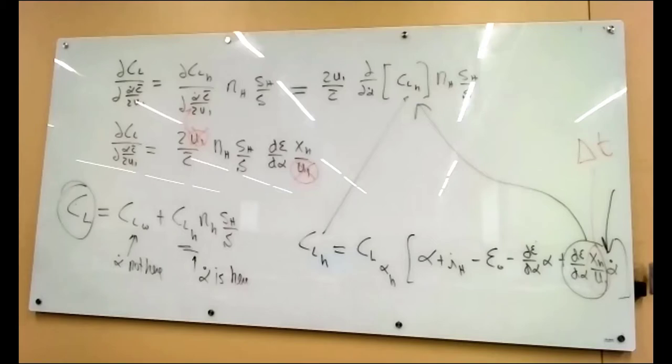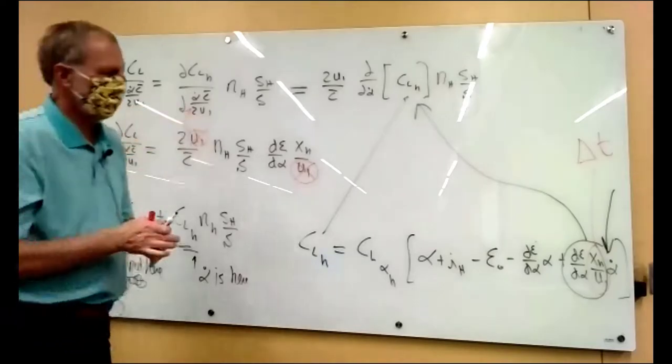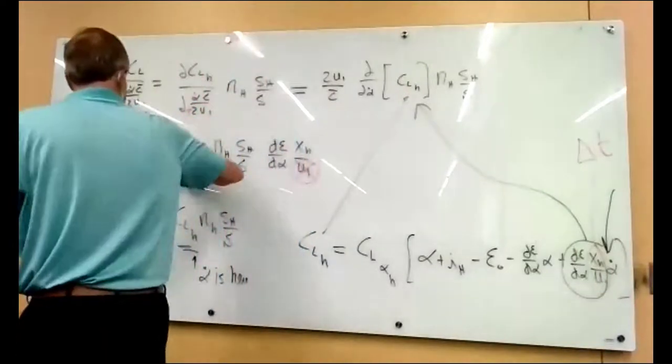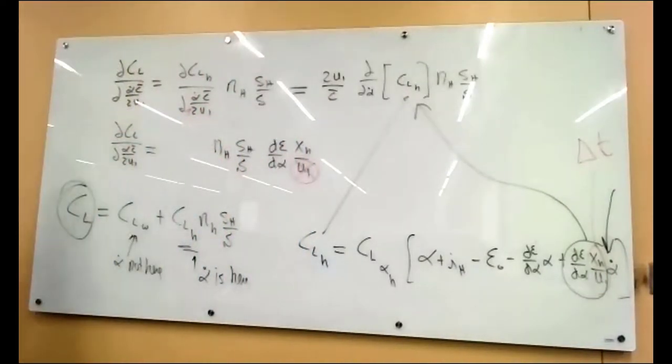Okay, so that's nice, but why is it such a big deal? It's because, let's say that we didn't non-dimensionalize. Then our term that's going to go into that matrix, the CL subscript alpha dot, would depend upon velocity, which means every different airspeed we flew our airplane, we'd have to recalculate that number to plug into the matrix.